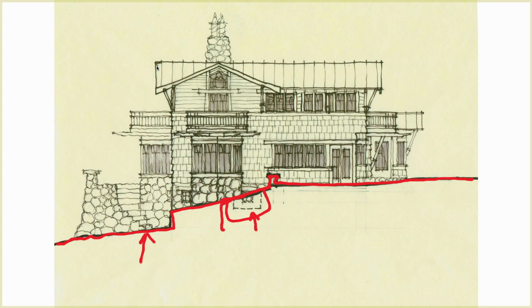But we can also look at the line weights in some other context. If you look at the line weight that is right along this edge, right here with those shingles, and I know I'm covering it up, so I'm going to wipe it off here for a second. That line right there is a really thick, bold line. It's not as thick as the section, it's not as thick as the ground, but it's the next thickest line. That, coupled with maybe the sides of this and the sides of that. That's because that's the next plane that we're seeing. It's the next thing that's closest to us.